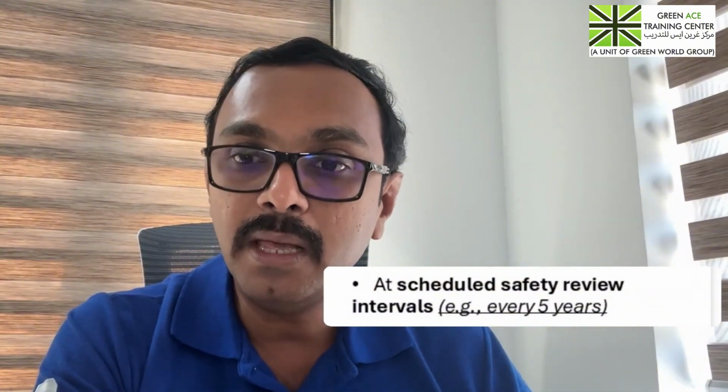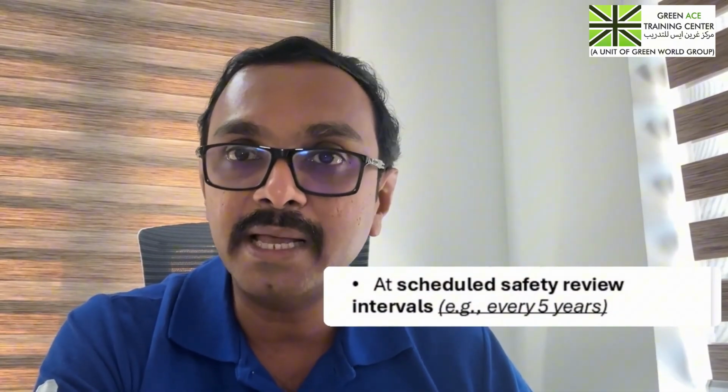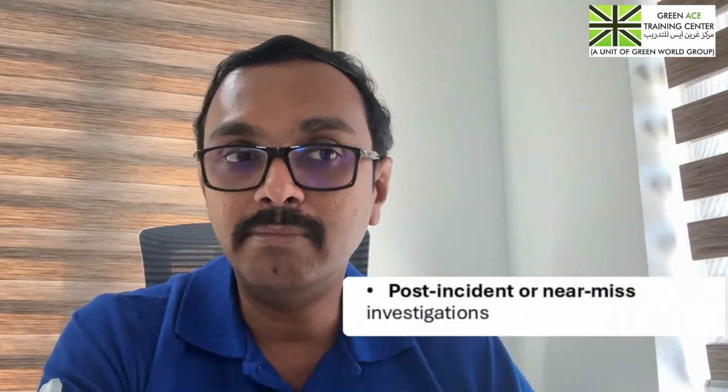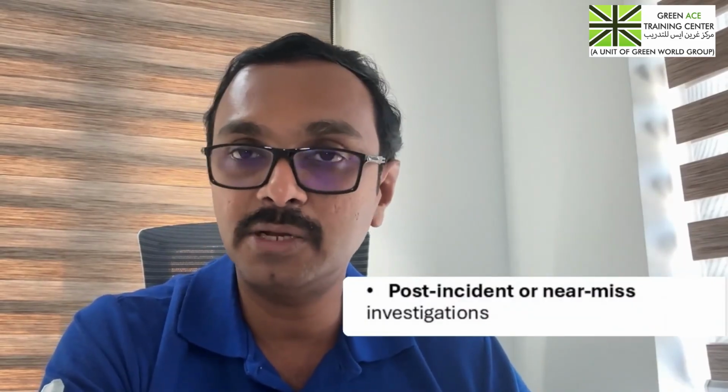In addition, HAZOP audits should also be scheduled on a periodic basis, which I would say is about once every 5 years. Please also understand that certain countries may have a different set of regulations, where this duration can be less or sometimes even higher, but 5 years is a good, suggested one. We also conduct a HAZOP following an incident or a major near miss or accident, to help understand what went wrong and how to prevent it. So these are the situations where we have to conduct a HAZOP audit.